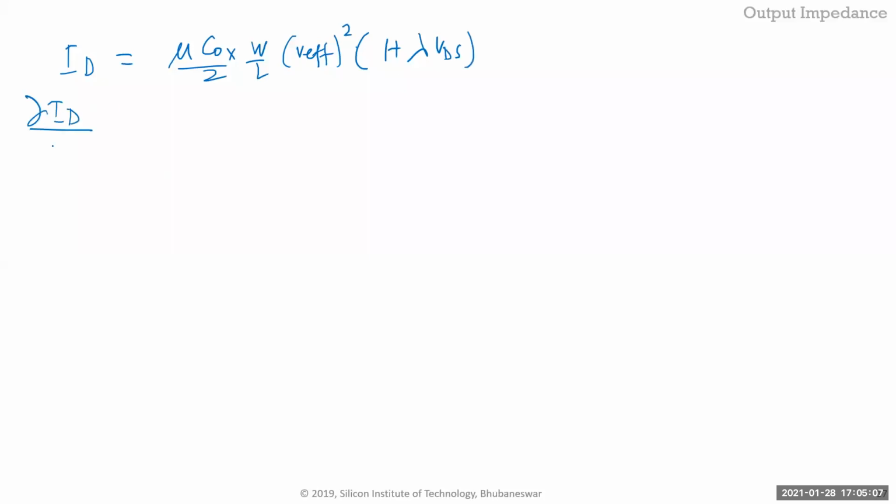All right, so next we're going to look at the output impedance, and this one we're going to take, obviously again, in saturation. So we'll have the V effective squared times 1 plus lambda VDS. But now we're going to do the partial derivative versus VDS with everything else constant, right? VGS0, also VDS0, VBS0. And if you do this, you'll see that the one term goes away.